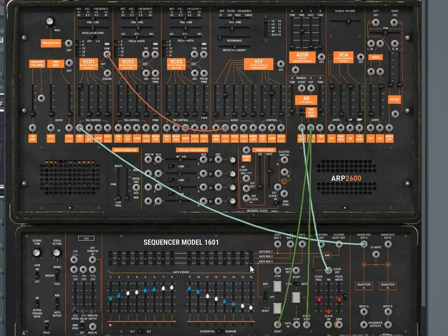And let's see. We'll just turn gate 3 on for every step of the sequence. This essentially turns the sequencer off, because as soon as the sequence starts, it's reset. Now, let's reset this to gate bus 2, and now the sequence should restart at the second note of every sequence, so we're just going to get a repeat of the first note of the sequence. And now I'm just going to step through and increase the length of the sequence by turning off gate bus 3.